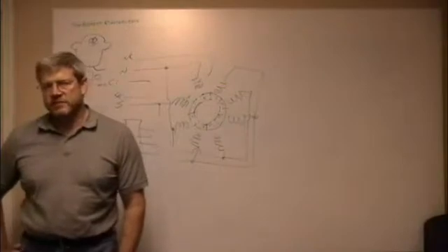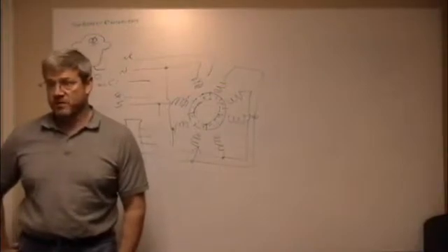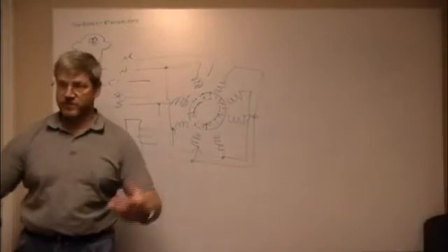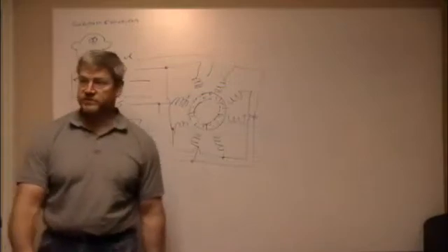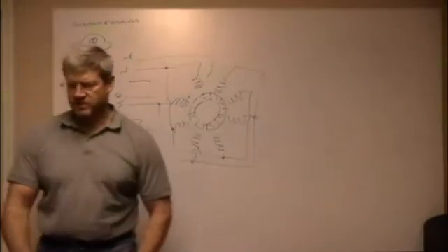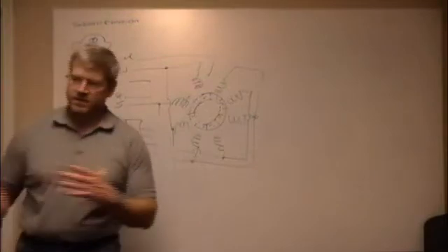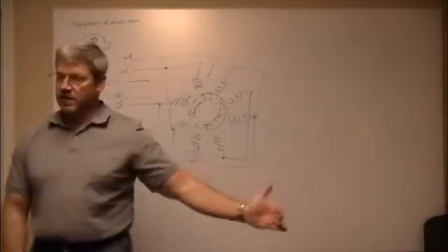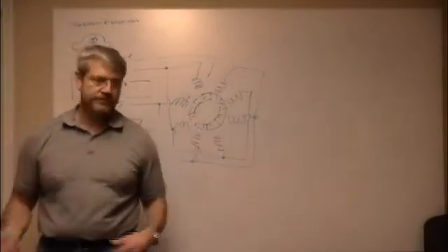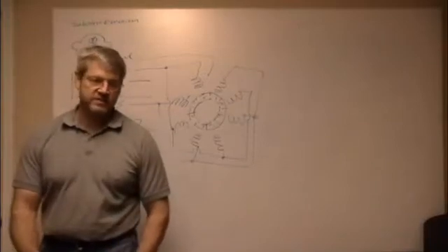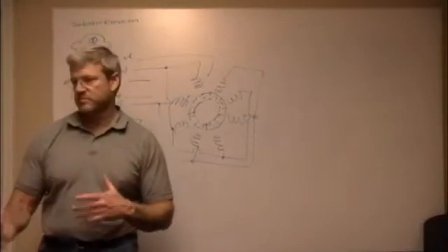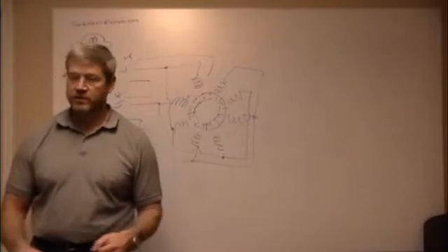A lot of the CNC mills, like a Bridgeport, if you buy the servo system for those, are actually DC servos. They're using the DC servo because they can turn it fast and get it to where it needs to go, and then slow it down. It's a lot more travel. There's trade-offs between the two, depending on what you want to do.